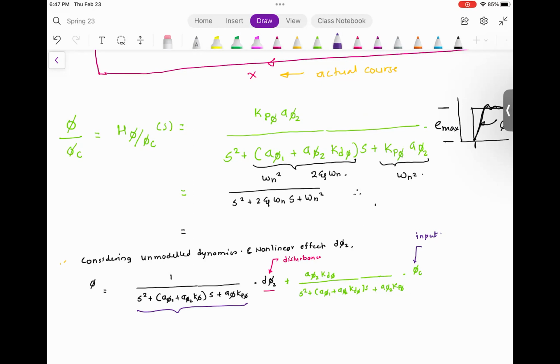That's steady. So that is the primary purpose of the control system designer, that even though you have a disturbance that is varying, at the end, either that complete disturbance should go away or it should get converted into a constant steady state error that we can quantify and cancel out. Steady state error cancellation is easy. You add a simple integrator term that you turn on, not all the time. You add a simple integrator term that you turn on when you are reaching the equilibrium position.